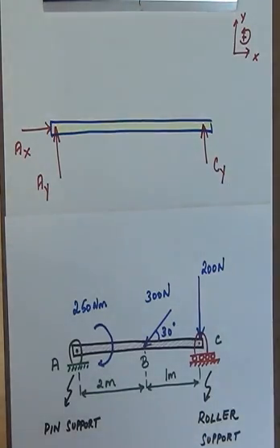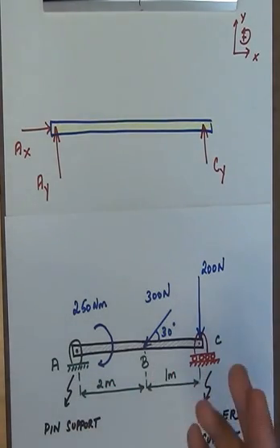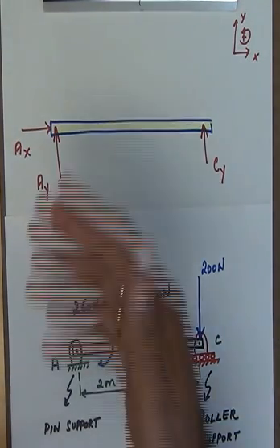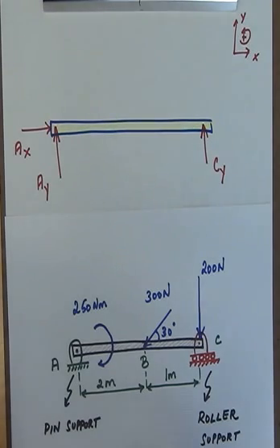There is no CX for the roller because the roller allows me to translate along the x-axis here, and no reaction moments, because we saw that by themselves rollers and rockers do not constrain any rotational motion. They allow you to rotate, which means that on the free body diagram you do not show a constraint reaction moment due to the roller or the pins.